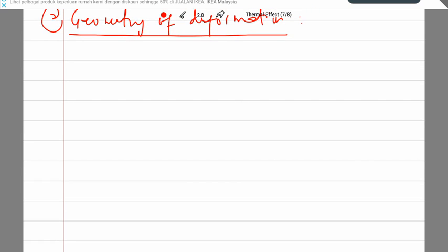Okay, so let's draw the deformation of the whole structure. So this is the CD rod, and if there's no rigid bar, it will elongate, let's say this much, caused by the increase in temperature. So this is delta T.